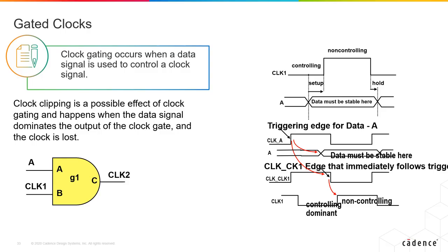In this example, we are specifying a slew of 0.38 nanoseconds on the rising edge of the ideal clock and a slew of 0.25 nanoseconds on the falling edge. Either a clock that drives A, the same as calling the clock object, or the root object will indirectly call the related ports. It can also be a multiple or an integer multiple of the clock root.